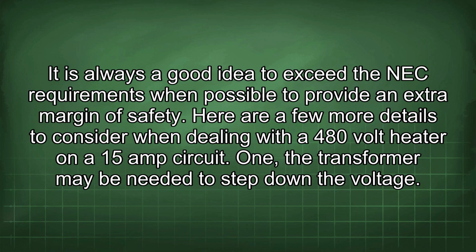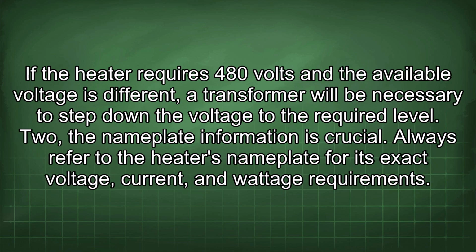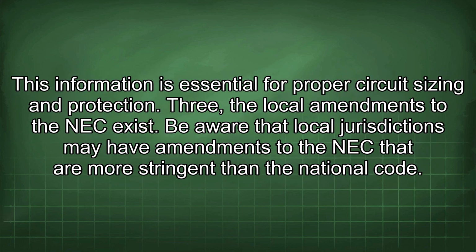Here are a few more details to consider when dealing with a 480-volt heater on a 15-amp circuit. 1. A transformer may be needed to step down the voltage. If the heater requires 480 volts and the available voltage is different, a transformer will be necessary to step down the voltage to the required level. 2. The nameplate information is crucial. Always refer to the heater's nameplate for its exact voltage, current, and wattage requirements. This information is essential for proper circuit sizing and protection.